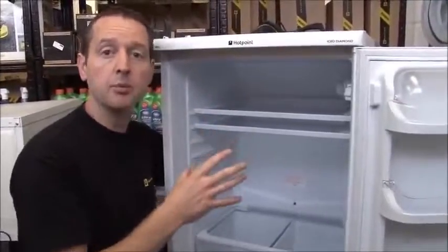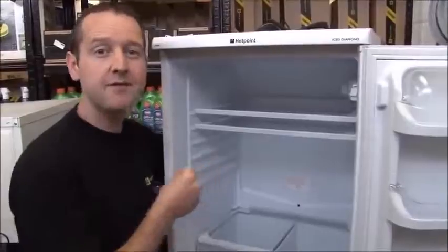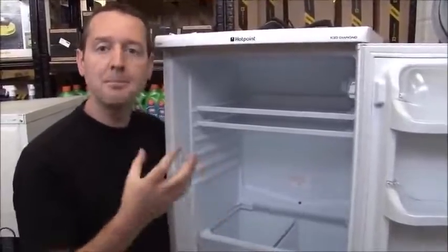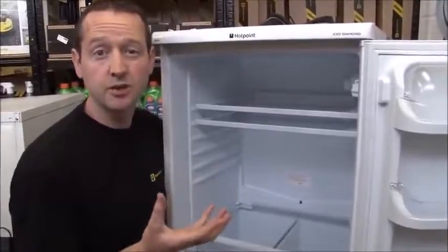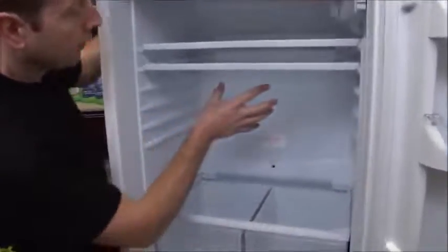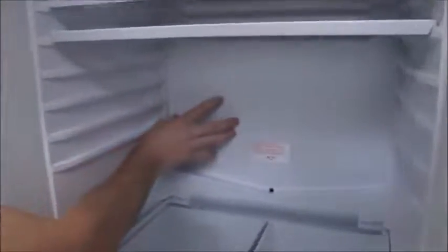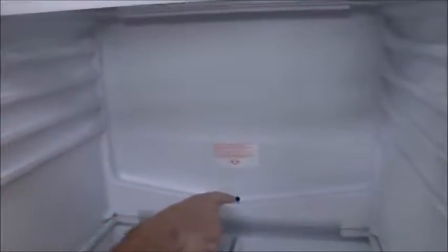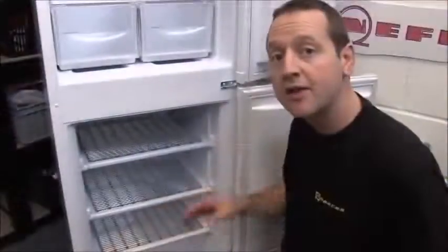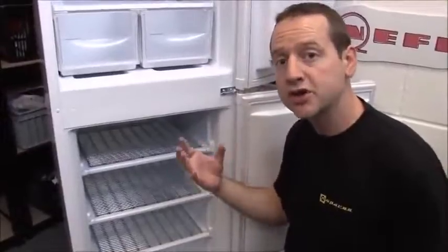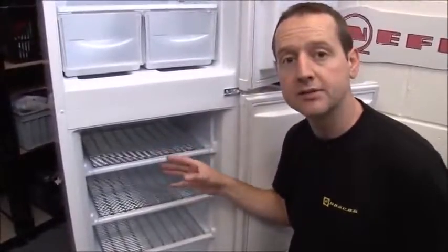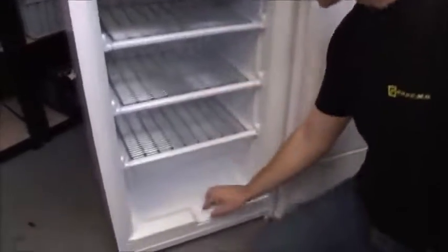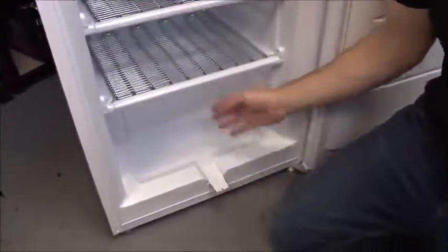Now the big problem with the whole refrigeration process is that every time we open the door we let moist air in, and that moist air condenses into water which needs to go somewhere. On a fridge it condenses onto this back panel where it drains down and out through this drain hole. And in the freezer compartment that moisture builds up as frost. In a freezer like this you'll need to manually defrost by turning it off and draining away the water as it melts.